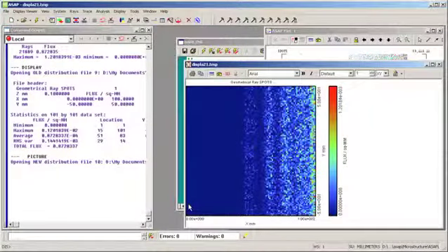When we look at the illumination at the top of the display, we see that we are only getting light on the far end of the display and getting nothing out on the front end. We see that a bare surface does not give us light over the entire display. We need microstructure to force light out of the plastic light guide and through the top of the display. Let's look at how we apply microstructure using the unit cell model.